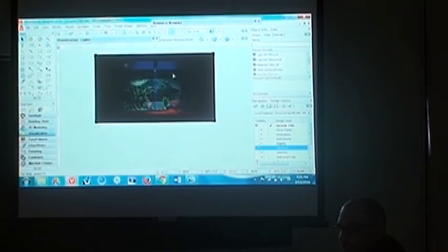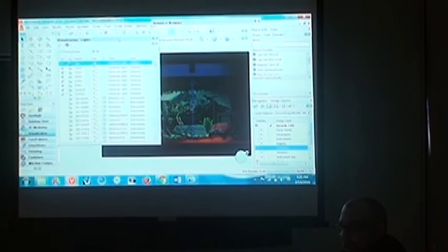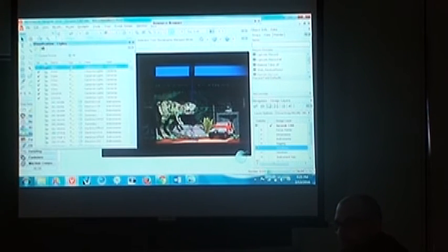This emitter setting right here is kind of a master for all those individual light objects. So if I want to bring the intensity down on all the emitters in the drawing at once, I can do that with the emitter brightness right here. I'm just going to leave that at 100, and I'm going to control the brightness, try to put this somewhere where we can still see it, with my visualization palette.